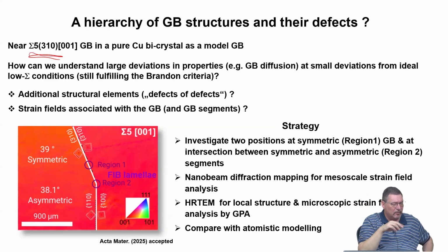And so basically because it's a diffraction signal, it's related to the orientation and the specificities of the crystal lattice that gives you the diffraction of these incoming electrons with the outcoming. And so this is a method of looking at the orientation distribution function of a polycrystalline material. Because you know the orientations of the crystals, you also know the nature of the boundaries, the interfaces between them.